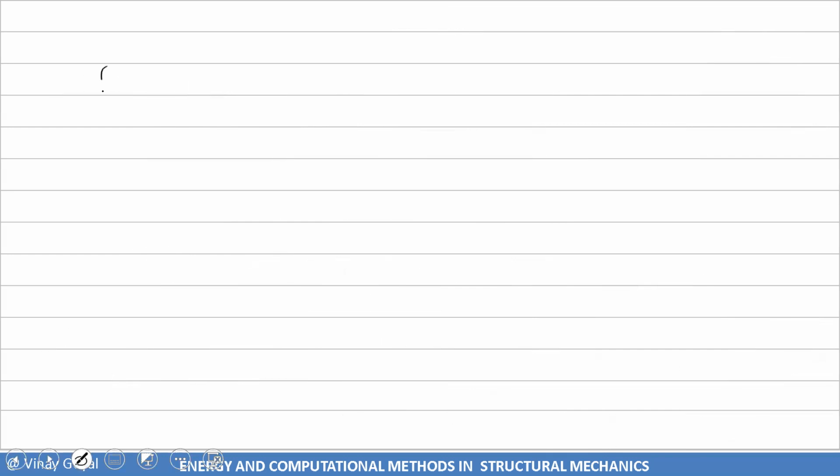So I have the integral over the volume, bi minus rho ui double dot plus sigma ij comma j, dv. So I combine all the terms together, and remember these del ui dv. And now I have the surface integrals that combine. So I have plus the integral over the part of the surface of the volume, which is ti.